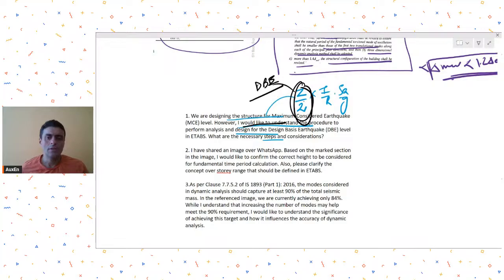In the upcoming code, I think instead of design basis earthquake, they have now gone ahead with an MC level earthquake. They have revised the return periods accordingly, and revised the zone factors, or the level of earthquake to MCE. So the procedure still remains the same, but what has been adjusted, because now we are considering higher level earthquakes, is that the load combination factors will be revised.